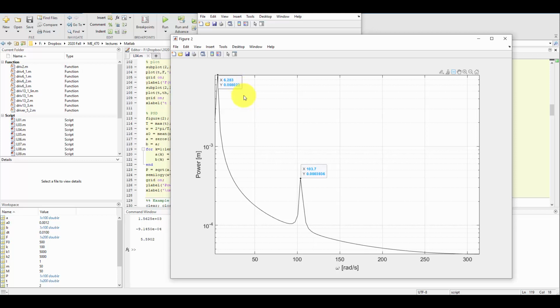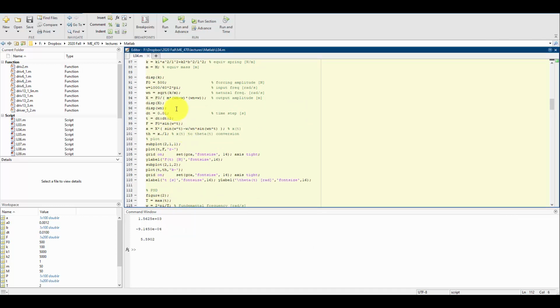But part of this is going to be caused by the resolution that I have. This is where kind of the closest it could find a peak based on my resolution, which was determined by that 2 seconds. So let's just see what happens. What if I sampled this for longer? Can I get closer to where these actual peaks should be? So going back into the code, here we go. Instead of doing it for 2 seconds, let me do it for 6 seconds.